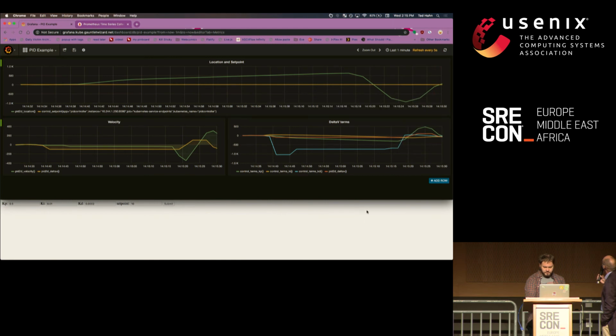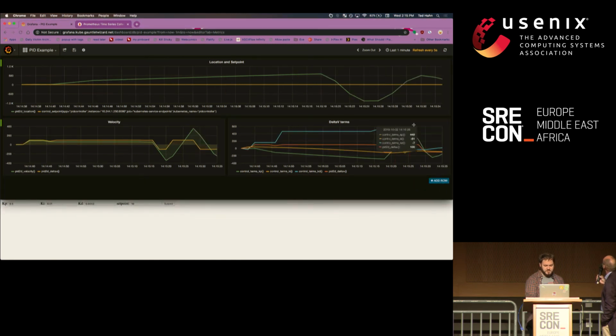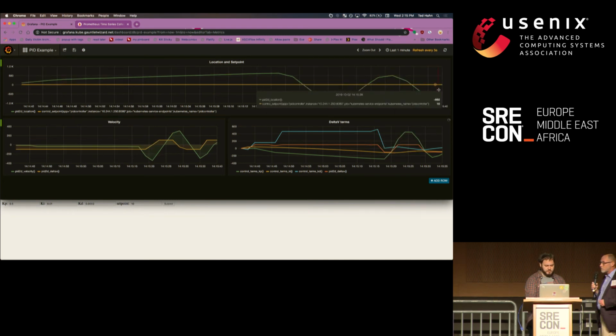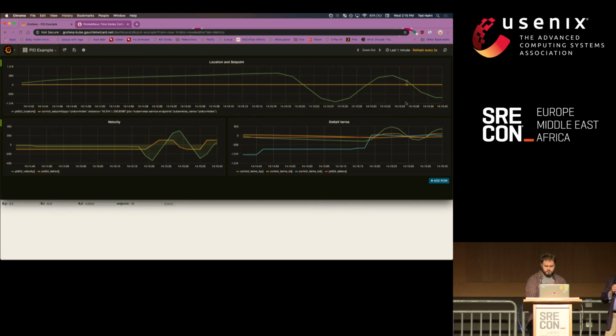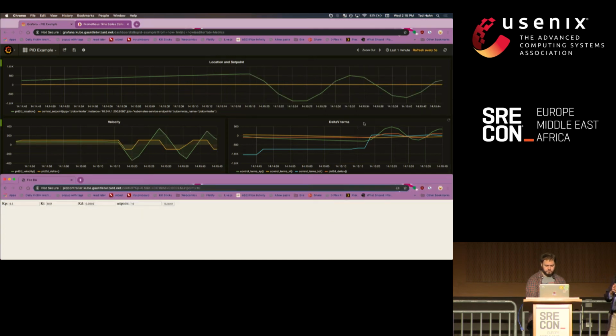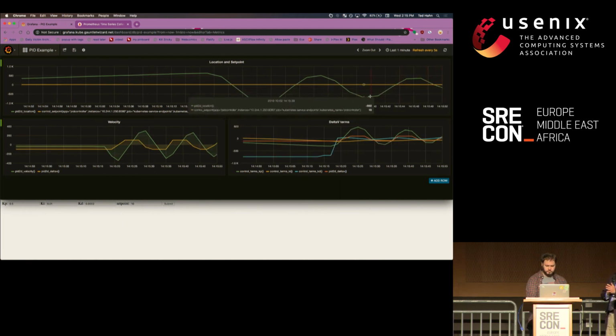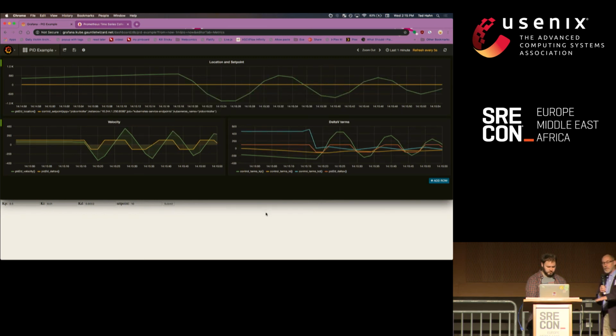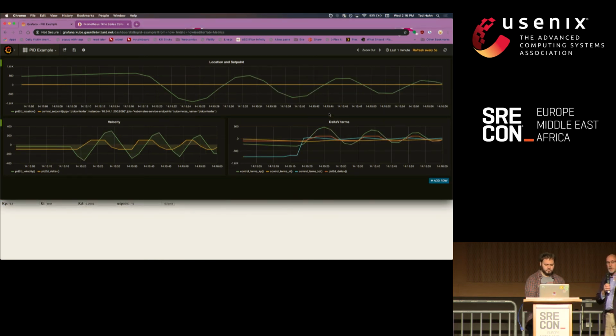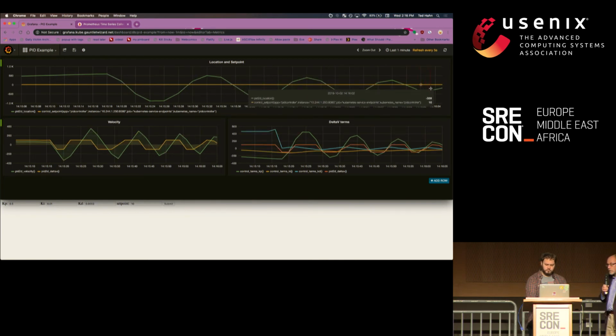Okay. So now we've adjusted the D term to overshoot less. And that's similar to when you're steering a ship: before you actually get to the direction that you want to head, you're going to start turning the steering wheel back because you know the ship is still going to have angular momentum that's going to keep it turning while you ease off on the steering. So that's what the D term is all about, stopping that turn sooner than the metrics and the eyeball tell you on course.